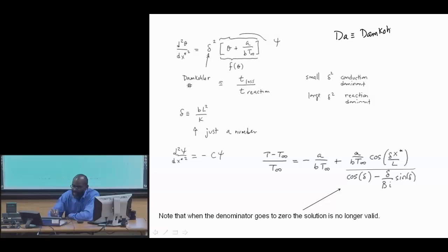If we solve this differential equation, again, not a hard differential equation to solve, we get a sine and a cosine, and when we apply the boundary conditions, we get T minus T infinity in terms of a constant and the sine and cosine. Remember, we set this problem up as being steady. We understand the thermal runaway is an unsteady process, but, and this is the important part, this particular solution shows that there are values of delta and this thing called this Bi.